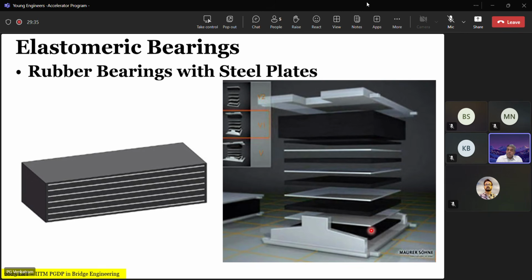They are never individual pieces like that. This is only for illustration. They actually put them inside a casing and bake them together, so they get bonded together. And when they are bonded, they look like this, generally black, and they have a top and bottom plate on which to seat them. Okay, and they sometimes have these projections on the side to give them rotational ability but no displacement ability, because this pin will lock into it.